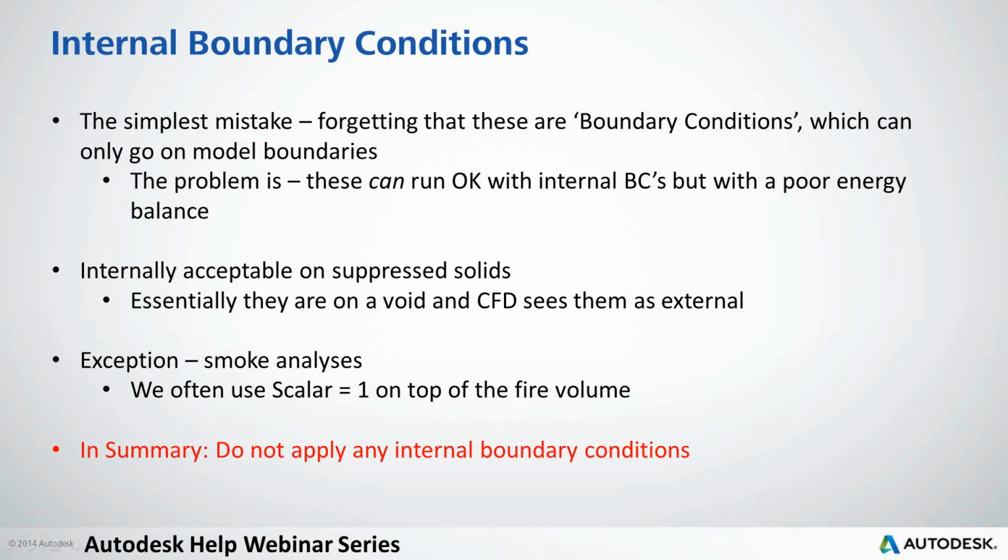There's one exception, and that's when we run a smoke or fire type analysis, and we would have a scalar 1 on the top of that fire, so the scalar of the fluid changes, or the scalar value through that volume, but otherwise we always avoid internal boundary conditions.